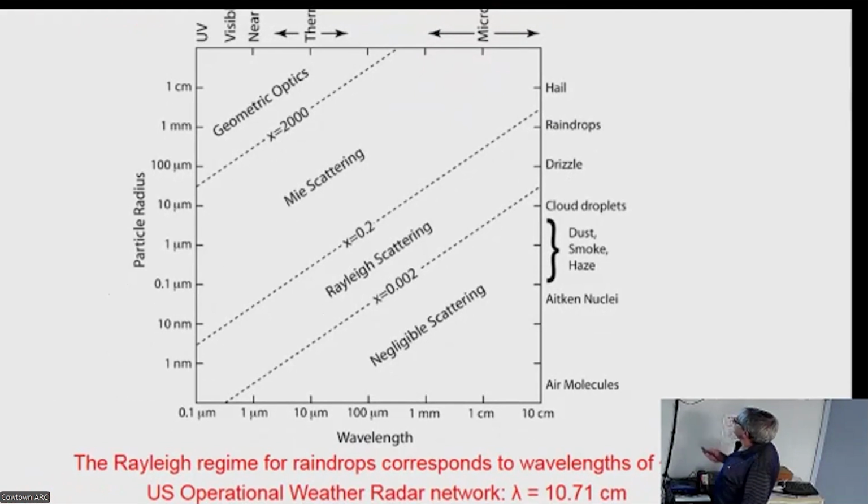But at any rate, the weather radars that we normally see on TV operate at 2 to 3 gigahertz. That's the S-band radar. Those are more useful because it's a low enough frequency you can penetrate out quite a ways to pick up phenomena 100 miles away or whatever. But you get more sensitivity if you move to 5 gigahertz, called C-band, or X-band in some cases, or if you want finer scale, 10 gigahertz. But you can't penetrate through as far, right?